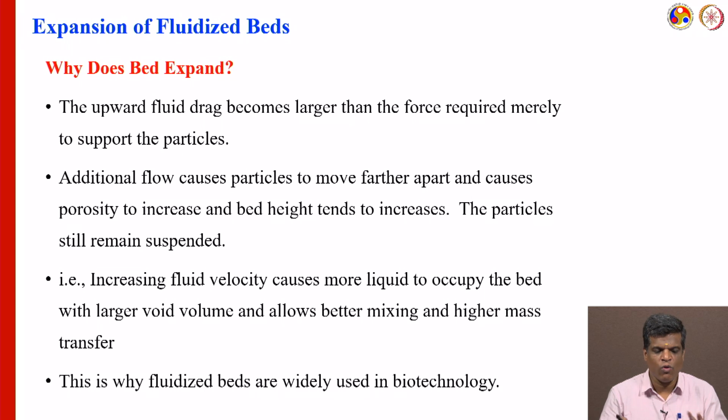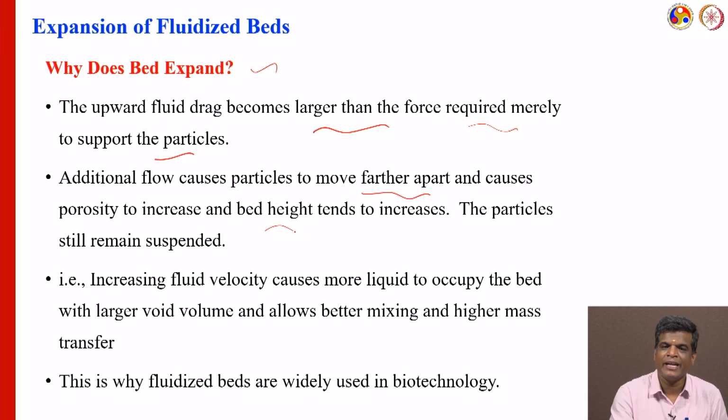So why does the bed need to expand? Because the upward drag force becomes larger than the force supporting the particles. Additional flow causes the particles to move further apart, the porosity increases, and the bed height also increases, while the particles remain suspended. With increasing fluid velocity, more liquid occupies the bed with a larger volume, allowing better mixing and better mass transfer here. That is why fluidized beds are widely used in biotechnology problems.